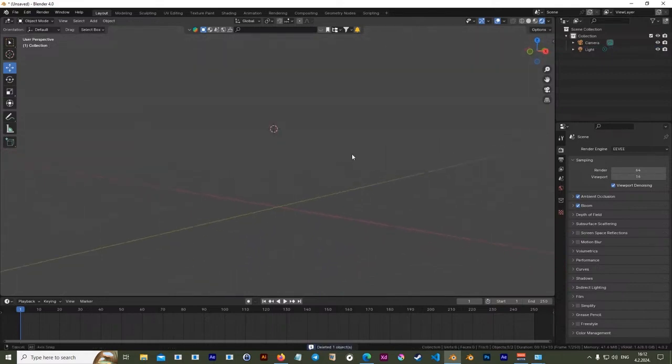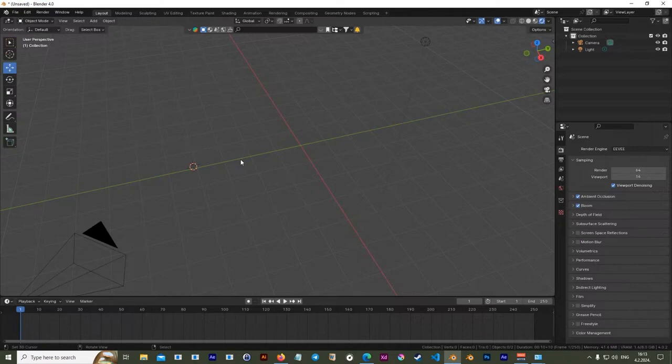One thing important to learn in Blender, as soon as you start working with it, is that you have this 3D cursor, and you can put it anywhere on a scene where you click, and you often click accidentally and move your 3D cursor. It's important to learn how to position that cursor back on the origin of your scene.